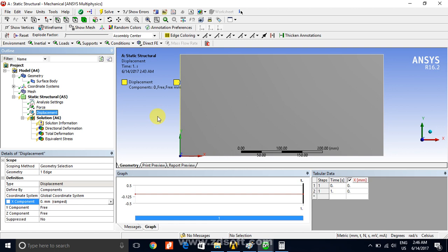It means the reaction has come here because we are stopping it here. We are cutting a section, and we are thinking that this half of the body is in equilibrium. This body is in equilibrium because an opposite force has been applied at this face, and the direction of this force is opposite to the other force. Because of the limitation of finite element, because a singular matrix would be created, we cannot apply the force in this direction. We have to apply a boundary condition.